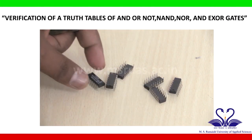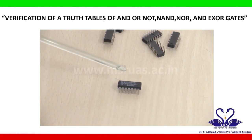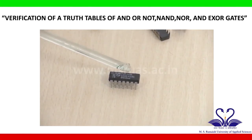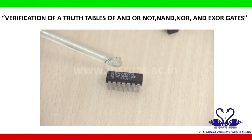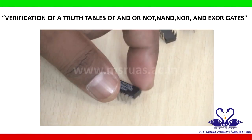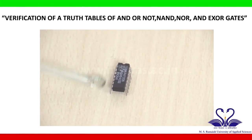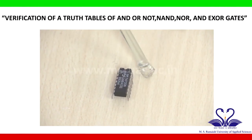For example, if you take one IC like this, on its top you can find a number, 74, then 2 digits, 7400. So this is a 7400 IC. And if you see this IC, it has totally 14 pins, one side 7 pins and another side 7 pins.